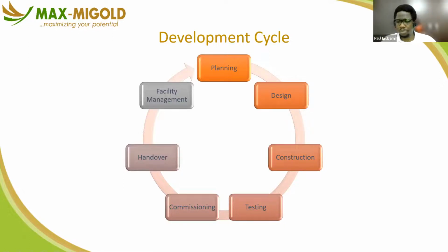So the whole idea of commissioning is gathering data about adequacy, and that is people focused. It's not necessarily focused on the building anymore. Testing focuses on the building, but commissioning focuses on the users. So that's why we have retro commissioning, which is the commissioning you can do when you do another renovation later in the life cycle of the property, or continuous commissioning, which is the data you keep gathering as the use of the facility increases to meet capacity over time.